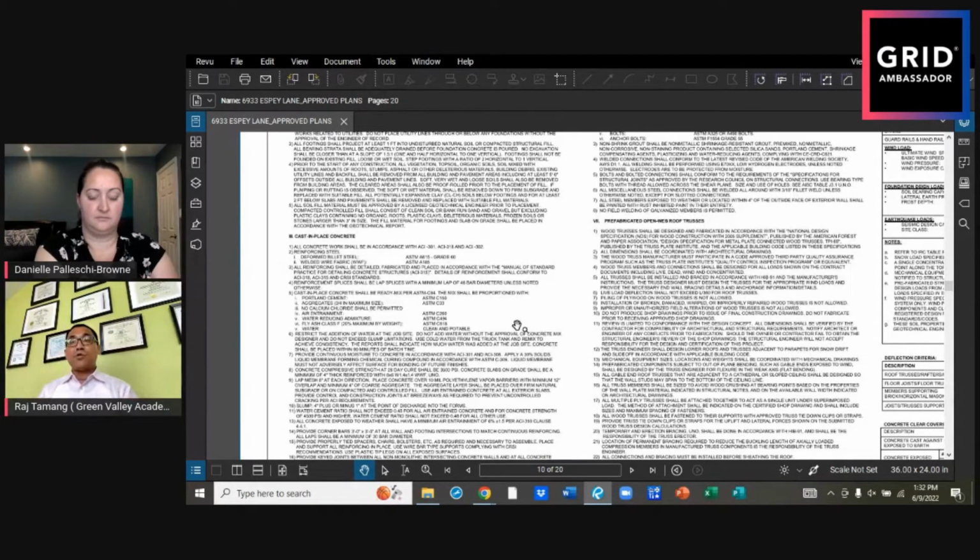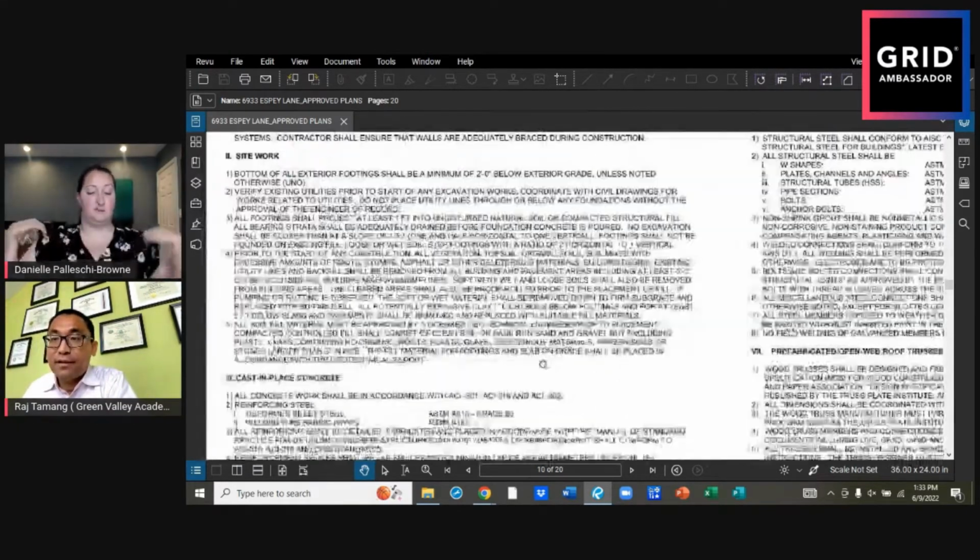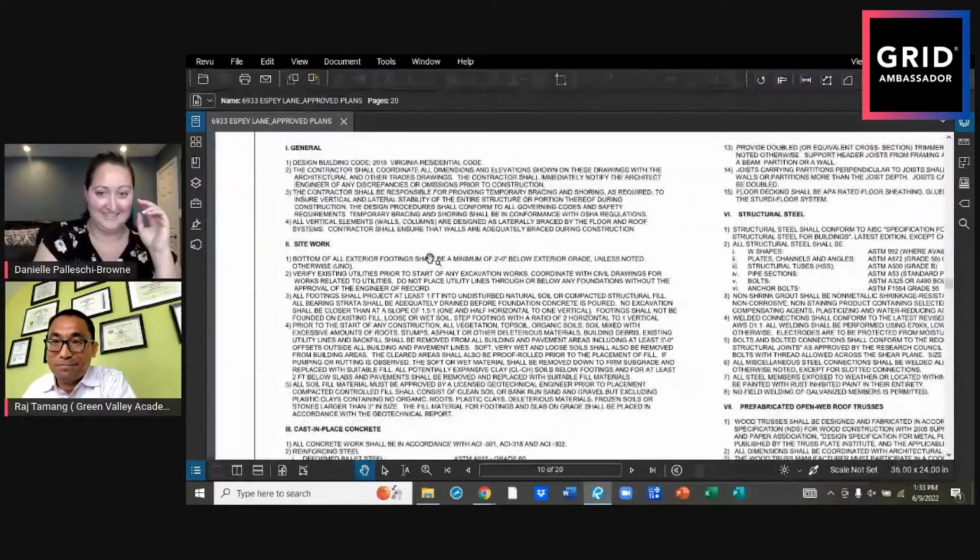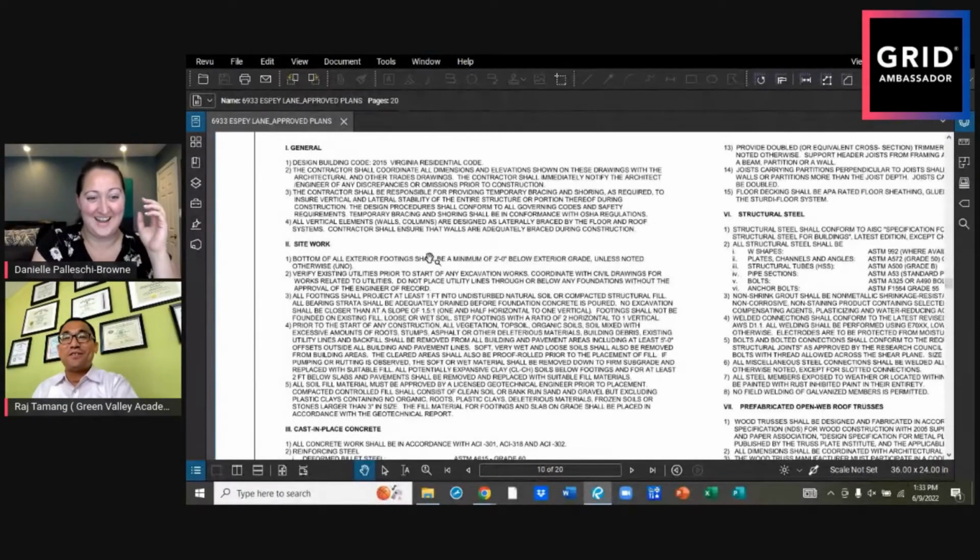There are some criteria you have to follow, because if it takes 2 or 3 hours for the concrete to come to the site, that's not good. Once you mix it, it has an initial setting time and starts gaining strength. So within a certain time frame, you have to pour the concrete. Otherwise, it's going to turn into a block. Correct, it's going to dry out.